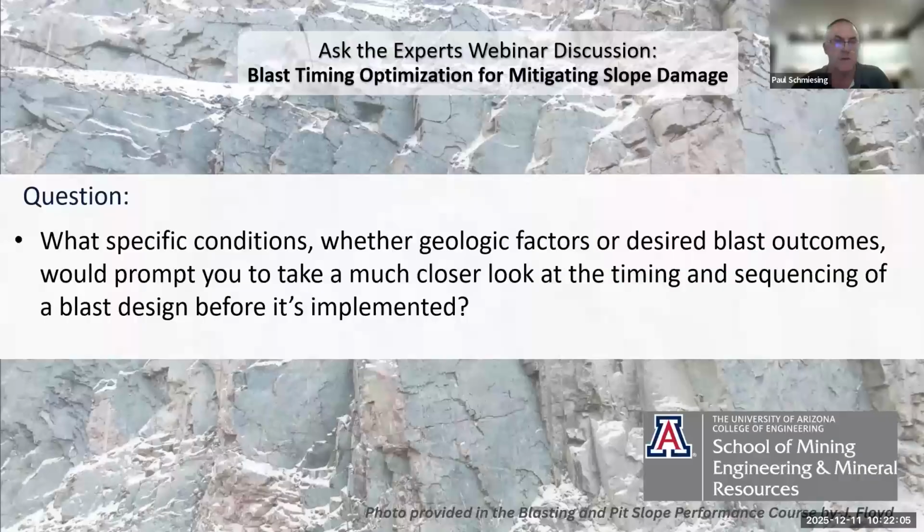Then it's, oh, there's a dike on this end, at the beginning third, and then there's a fault on the other third. So now we know in this middle section, it was being controlled by a dike and a fault. Sure enough, the ground's really sheared up in that zone. So the timing we're using in that section wasn't right. Then we'll try to create a signature hole for that domain. What I'm finding is that through that analysis we pick up on the different domains we're dealing with, and generally one timing for the whole bench isn't the same timing we should be using.